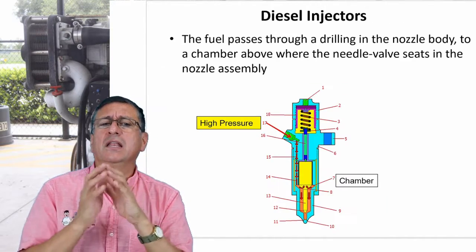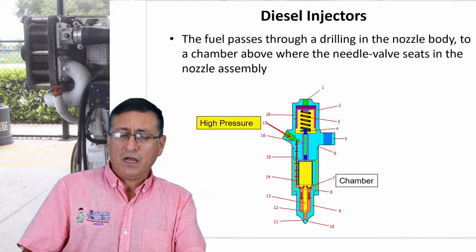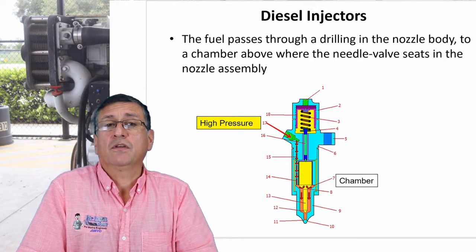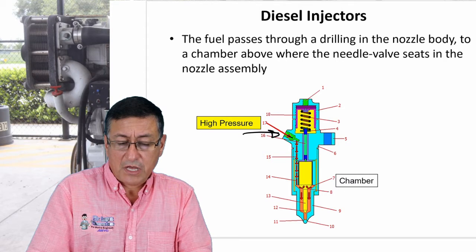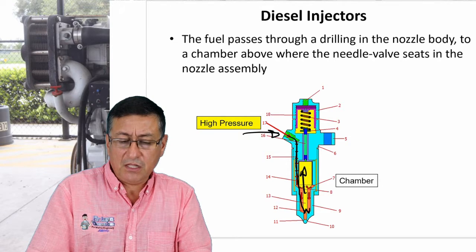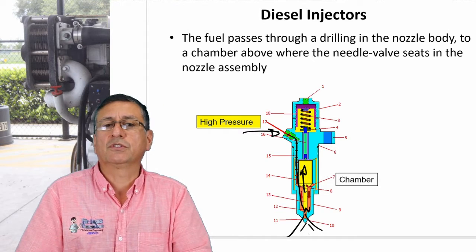What happens internally in the mechanical fuel injector is very simple. Remember, in the majority of the fuel injectors, the fuel enters on one of the sides, the fuel goes down, and in this shoulder it produces a pressure, lifts the needle, and after that the fuel enters and penetrates the combustion chamber.